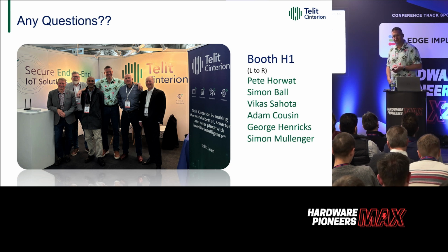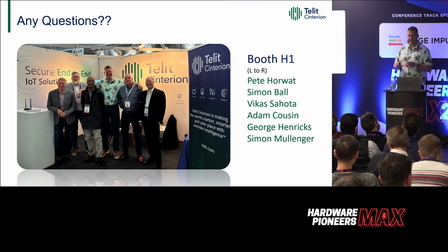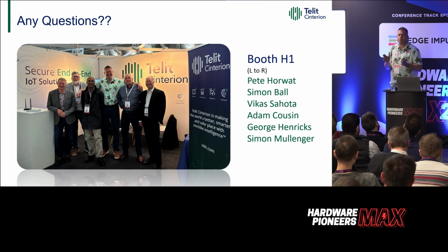That's the problem. You've just got to be able to see the satellite. But yeah, I saw a demo the other day of it working, which is really nice. The problem is that there are no AT commands on a modem that support it yet, so it was through the QXDM interface. So it was like a blink and you miss it scenario if anyone's ever used that interface on a Qualcomm device before. But what we're talking about is probably towards the end of this year, unless my learned friend at Sony Altair can give me any better news. Probably towards the end of this year when it comes to firmware availability and actual usability of this stuff through a cellular modem provider.